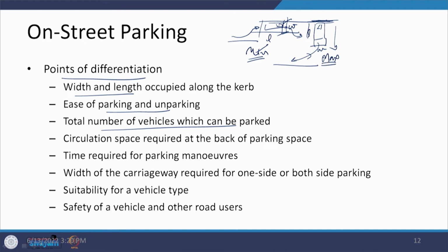So, that is also an important issue, because you have to see what is the demand in that area, and accordingly this supply has to be adjusted. So, supply versus demand is going to be settled by way of even the use of angled parking. Circulation space required at the back of the parking area, we have talked about it. Time required for parking maneuvers depending on how complex it is. So, if it is a parallel parking, probably it may take more time, but if it is an angled parking, then this may take less time to park or unpark a vehicle.